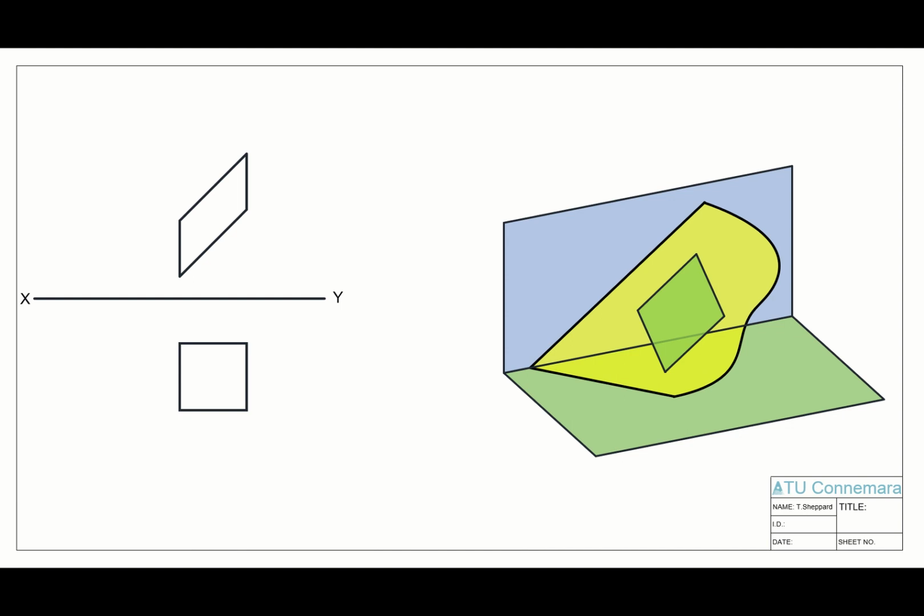So the beginning of this method starts off with just finding a true length line on our lamina. To find a true length line, the first thing we do is we draw our horizontal line on the actual lamina in elevation. So there is our horizontal line from any of our points. I picked this point here, but I could have picked this point over here. Actually, you don't want to go across the two here because this is vertical. You wouldn't be able to find where it is in our plan view. So a little bit of planning with that work goes a long way.